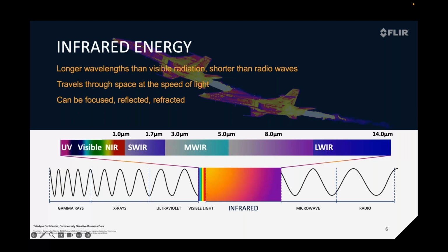The next one is SWIR, also standing for shortwave infrared. This spans from 1.4 to 3 microns, or maybe 0.7 to 2 microns. It's a region dominated by reflections and absorption. Typical detector materials here could be InGaAs, or indium gallium arsenide. Also, there's colloidal quantum dot, there's SLS, InSb, and MCT that can run in some of these bands. And although it's still not classically a thermal band, SWIR cameras can be calibrated for high temperatures starting around 400 degrees Celsius, since that's about the point where thermal emissions overtake the signal created by reflections.